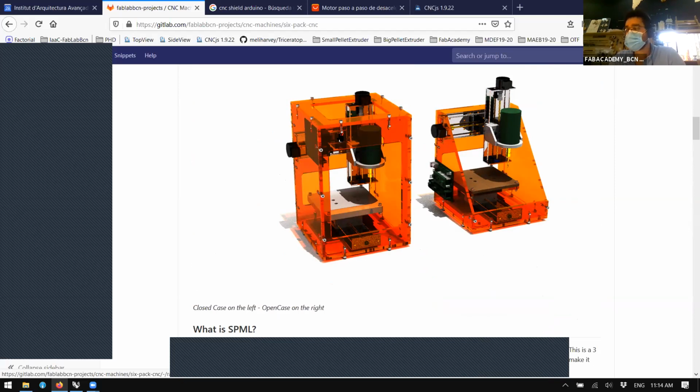So actually we have two types of screws in this machine, 3mm for the frame and 2mm to fix electronics, the rails, and the end stops. But even so, screws are usually sold in lengths of 3mm, 4mm, 5mm, 8mm, 10mm, 12mm, 15mm, 20mm, 25, 30, 35, 40, 42, 45, and 50 usually. And after that you go to 80.